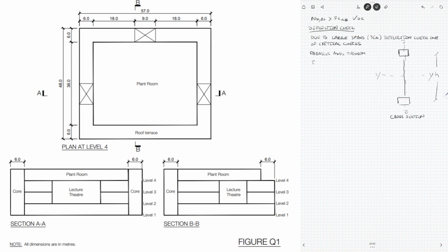That creates a bending moment that is then distributed as a couple of forces between the top and bottom chord. The worst case scenario is always between tension and compression of the same magnitude. It's always the compression. So I check the actual compression capacity, just following the typical capacity resistance to compressive forces and buckling following the Eurocodes.